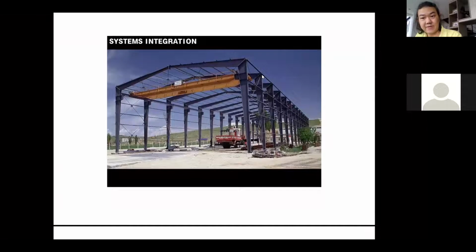Okay, we have the brace frame for the factory or the warehouse, and you can see very clearly that in this direction, when the wind comes in this direction, it's the frame itself that has to take the load. So the frame in this direction must be pretty strong because there's no help, and each frame will be all alone by itself. But let me erase this. When the wind comes in this direction, what you will have to withstand the wind in this direction is the entire frame in this, right?